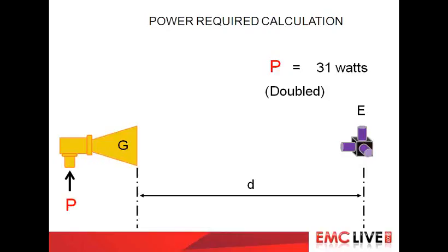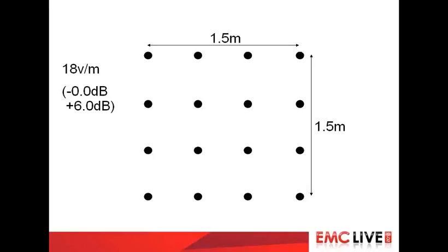So that break off there was basically to describe the impact of beamwidth, now that we're into high frequency testing. Now that we have narrower beamwidths and higher gain, we need to take the beamwidth into account. So if we look again at our requirement, and bearing in mind we have the situation where we've defined our zone of interest and discount anything either side of it, it would be nice to also define our degree of freedom in terms of the allowed parameters, that is, we cannot exceed +6 dB.